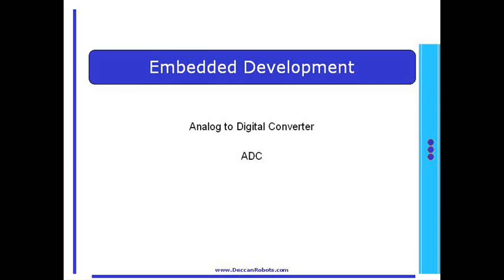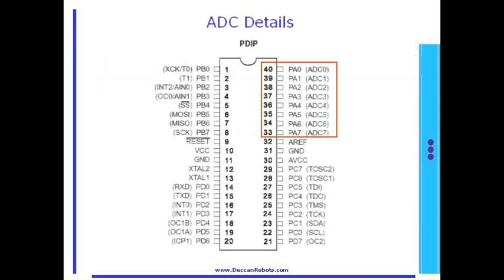An analog-to-digital converter is a technique which converts a continuous analog signal into sampled numerical values representing the original signal. The input to an analog-to-digital converter (ADC) consists of a variable voltage. The system generates digital values which are a combination of binary 0 and 1. ATmega32 has 8 such converters inbuilt. These built-in ADCs can provide up to a 10-bit result value. Let's see more details of ADC and its applications.